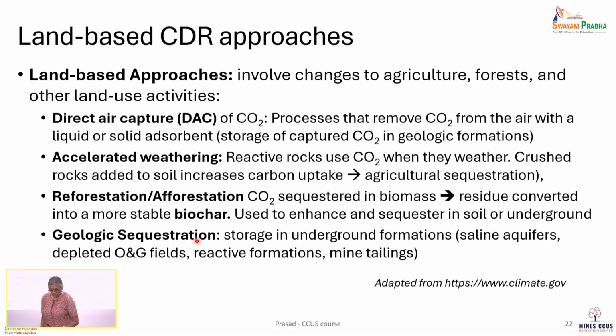When we look at geologic sequestration, we are examining formations where we can store about a kilometer at least in the subsurface, often more. The reason we want to go deeper, there is a sweet spot, because as you go deeper, you have higher pressure, and so you cannot make use of the pressure differential as much. If you're too shallow, you're very close to the water table. So we want to be deep, but we don't want to be too deep.